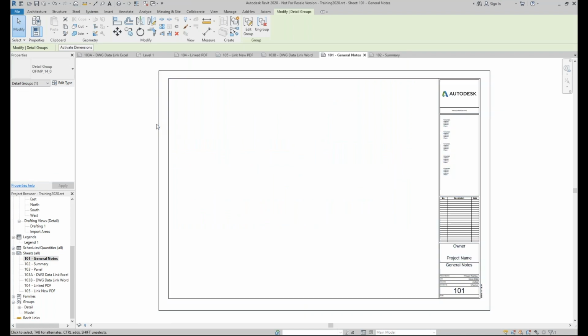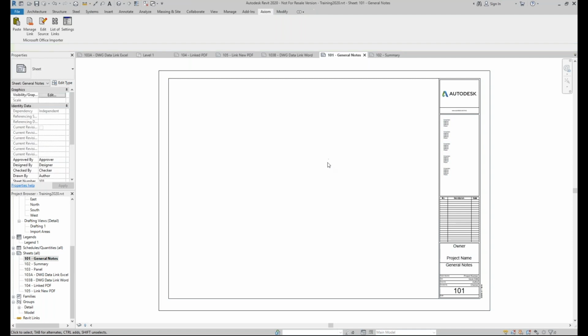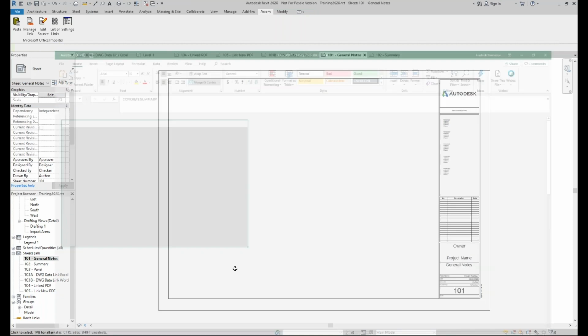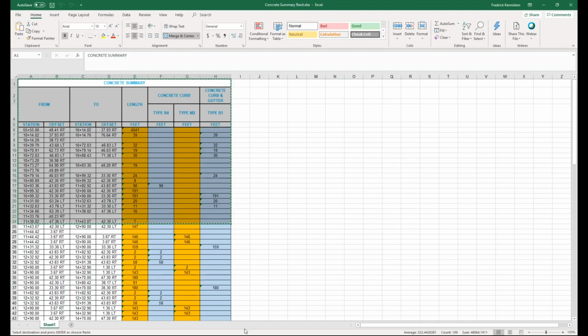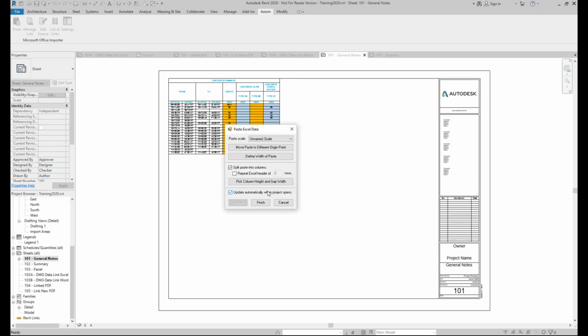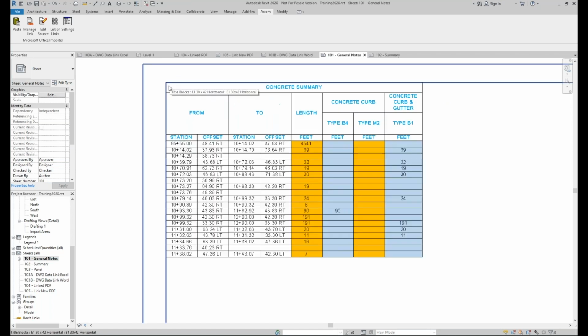So with that, what I'm going to do is go back to another sheet here, and I'm going to paste, in this case, a portion of an Excel file. I'll just highlight what I want, do a copy. And again, I won't be able to grab this data and just do an insert using the text insertion point for Excel, but I can easily paste Excel data into a Revit project file with this program. I click the paste button, it analyzes the data, again turns it into Revit objects. More on that in a moment for Excel. Click finish, and when I zoom in, there's the formatting.